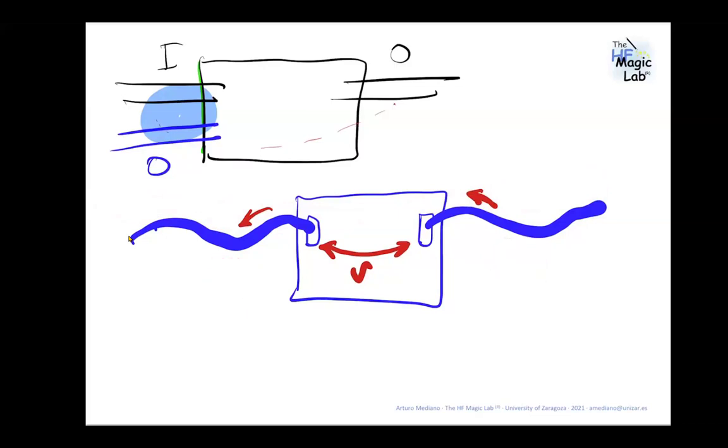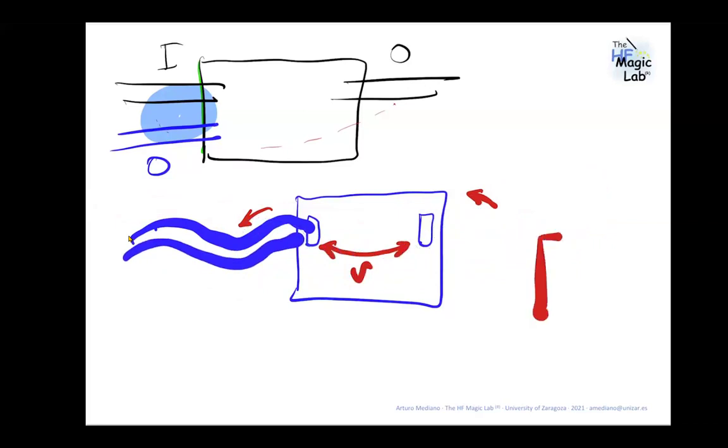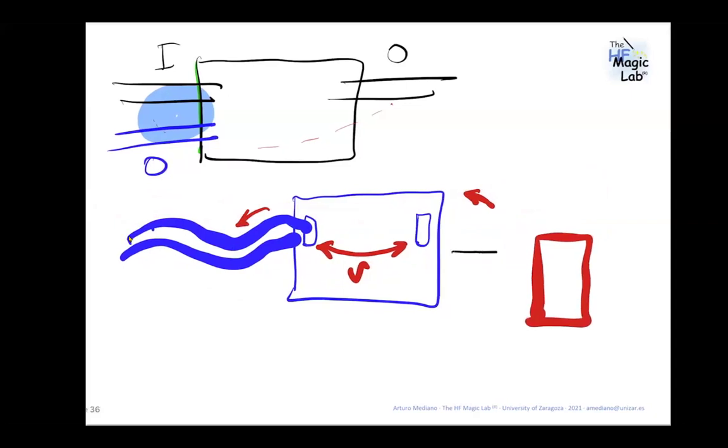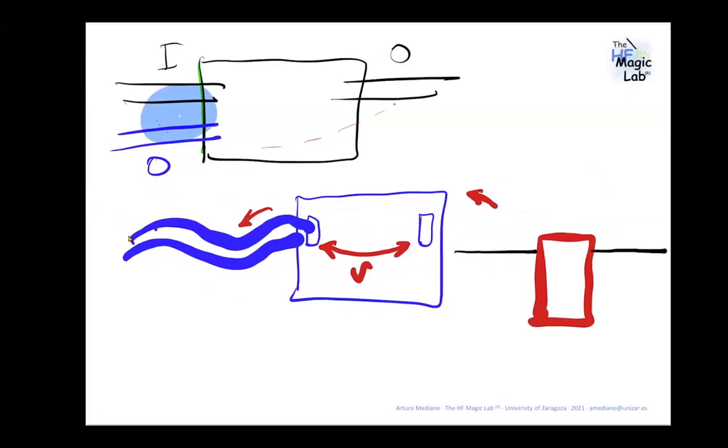If you put this cable in the same area, it's like having one antenna, remember the antenna I was using in my demo. To have a good antenna, this arm and this arm must be separated from each other. If you put the arms one close to the other, this will not radiate, okay? So with connectors and cables that are close to each other, you minimize the possibility of having parasitic dipoles. But you have advantages and disadvantages.